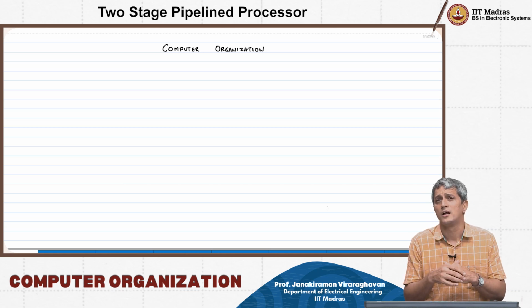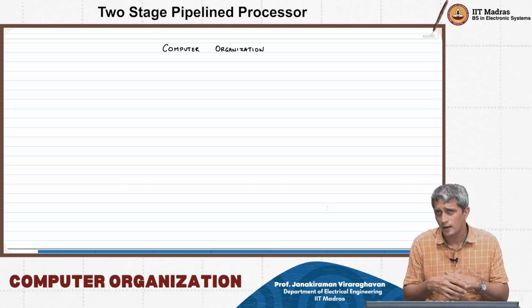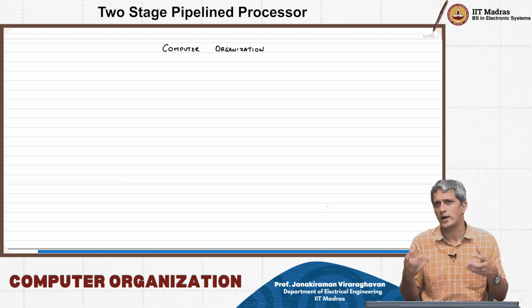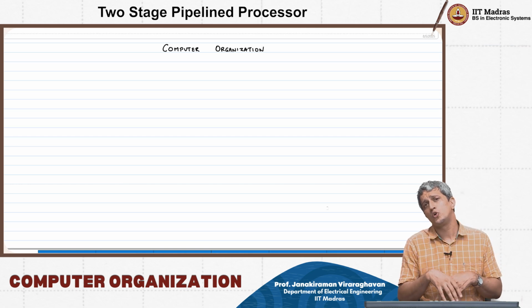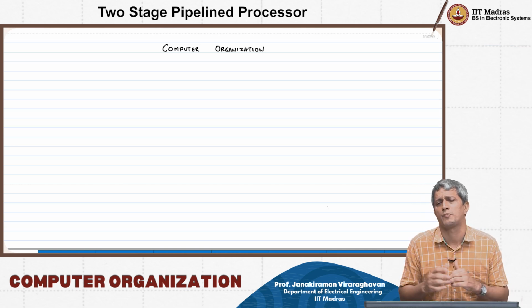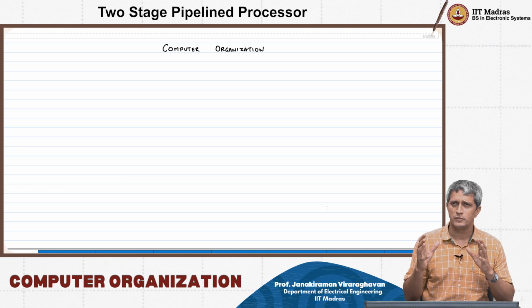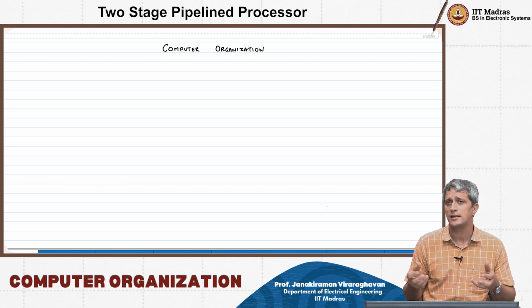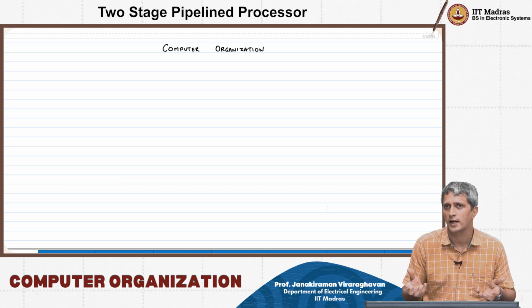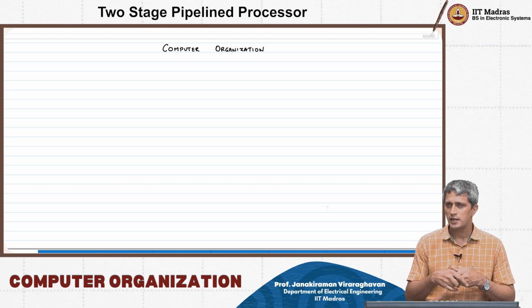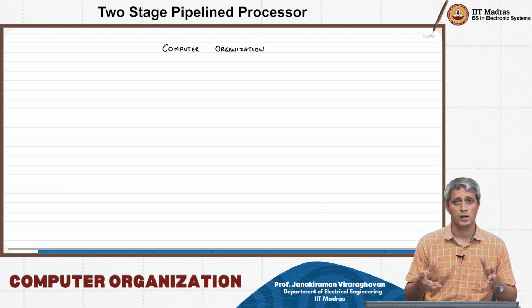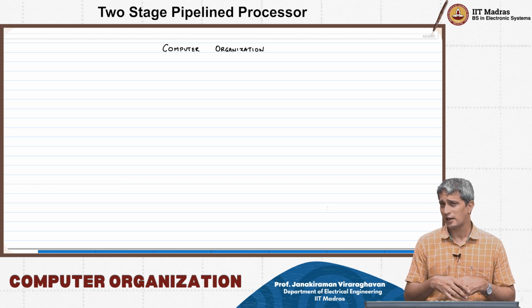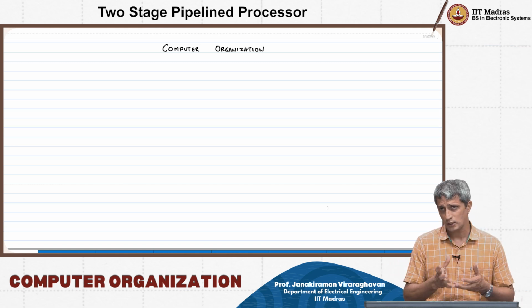Of course, doing it for a 5-stage pipeline is quite a difficult task for us to draw all those signals. So I think it's a good idea for us to look at a very simple 2-stage pipeline. That also helps us understand that the choice of five is not sacrosanct. It is not necessary that you have to make only 5-stage pipelines. You can as well have smaller or more stages of pipeline. It really depends on delay, your architecture and so on.